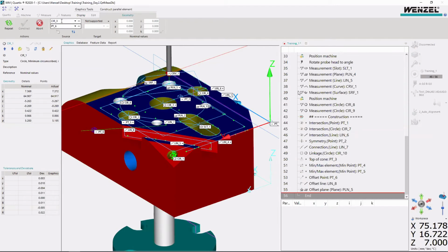First we have 2 columns, and now this swap element will be useful. For the first column, we need to enter the element which we want to have a direction parallel to. Meaning to say that we need to construct a line parallel to line 8.